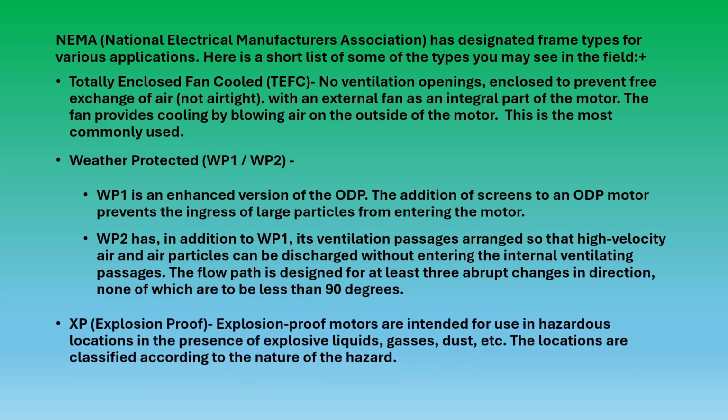Finally, in this example, we have XP, which is explosion proof. Explosion proof motors are intended for use in hazardous locations in the presence of explosive liquids, gases, dust, etc. Locations are classified according to the nature of the hazard.